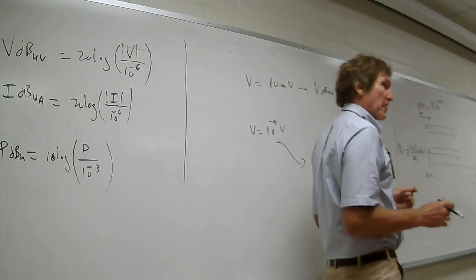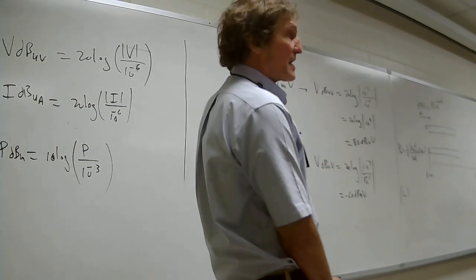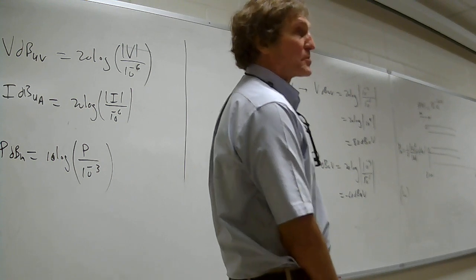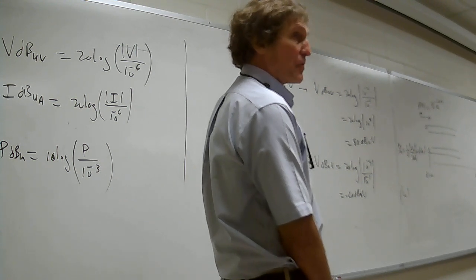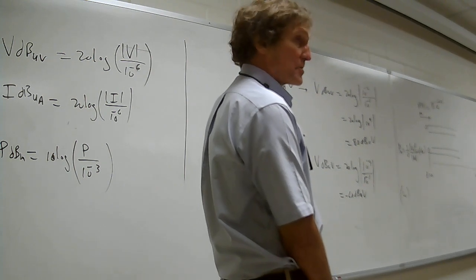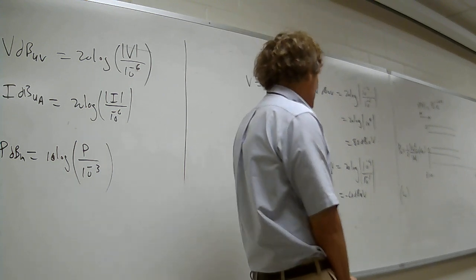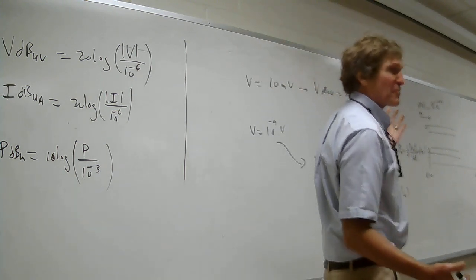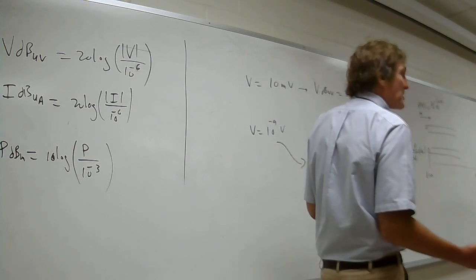Do y'all follow me? Now the reason we use dB microvolts and not volts is because when you have orders and orders of magnitude, like 6, 10 orders of magnitude of difference in voltage is possible, and happens a lot when you have signal and noise, and you get just noise, no signal. They use this because it compresses the actual domain down to roughly plus or minus, it's really going to be about 100 dB either way.